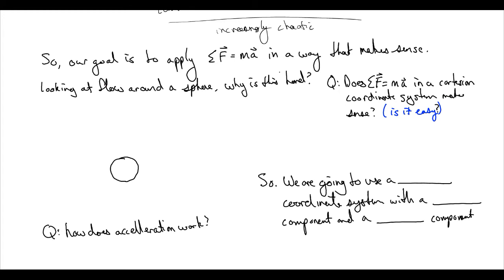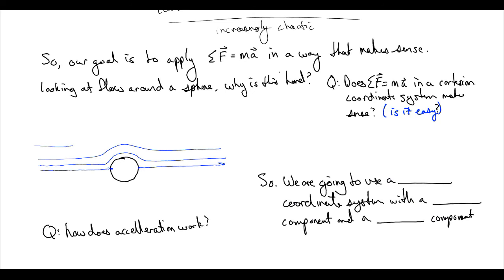So if we look at flow around a sphere, even if we're just doing laminar flow around a sphere, we have one streamline that's coming in dead ending because it hits the sphere completely symmetrically, so it just comes to a complete stop. And there's one that stopped and then accelerates away like that. And then basically all of our streamlines will follow the sphere around like this.